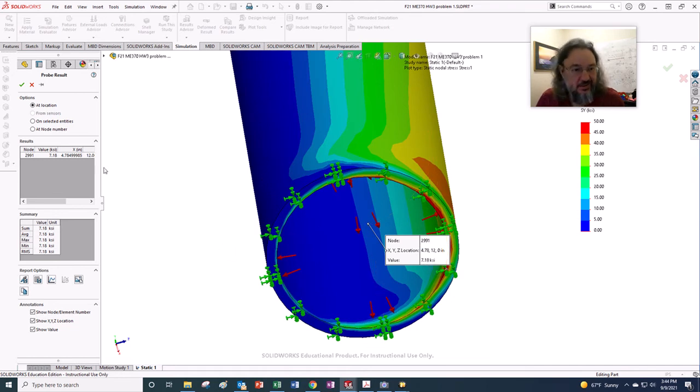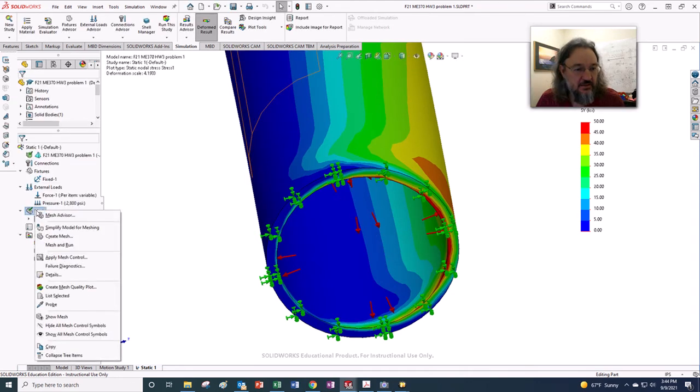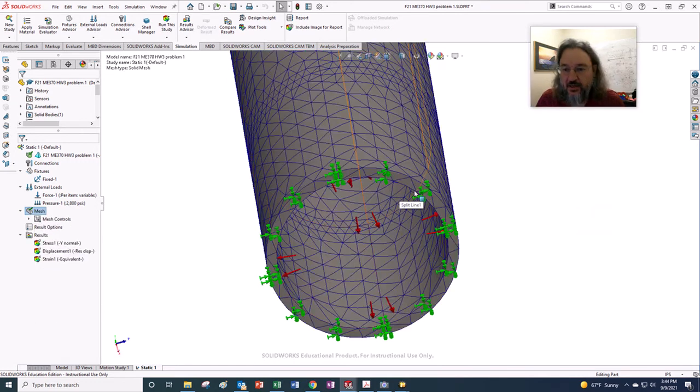I meant to say this a second ago, but short attention span, I forgot. One test we should look for is how many elements there are through the thickness of a part, right? I can think of them as triangles, but I guess they're tetrahedral stress elements.